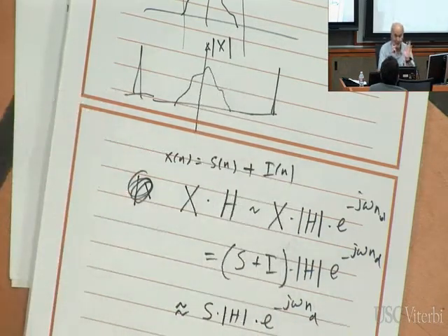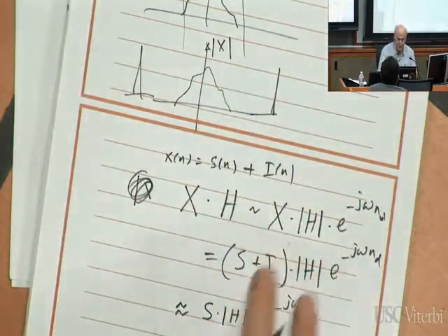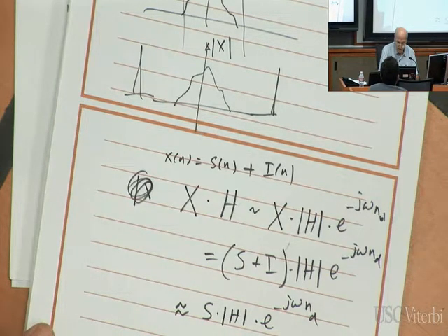That's why it's important to go through the filter if you have noise outside of the bandwidth of the signal. In that case, the filter is able to separate it out, get rid of it, and if it's linear phase, then you have that. That is just, to a good approximation, s of n minus n sub d. See? That's why linear phase filters are very important.